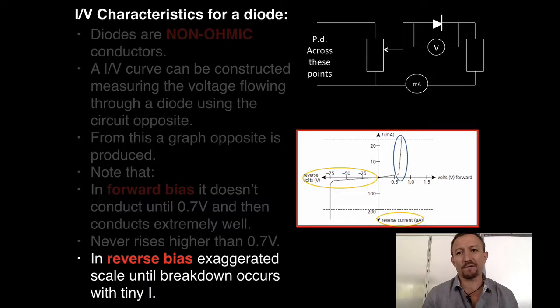So it prevents the current flowing through at high voltages, and the result is you're going to protect the system. The key thing as students is that often in an exam you might be given one of these curves and expected to read into it the idea of forward bias, i.e. you read the curve on the right hand side, or reverse bias where you're working on the left hand side of the graph. And it's important that you understand those two concepts. As I say, it's going to make life easier when you read the question. You're looking for forward bias or reverse bias, and that tells you where to look on the graph. Once you're able to look on the graph, the result is you can work out various voltages, etc., and then you can be asked questions accordingly. So that basically runs through the current and voltage characteristics for a diode.